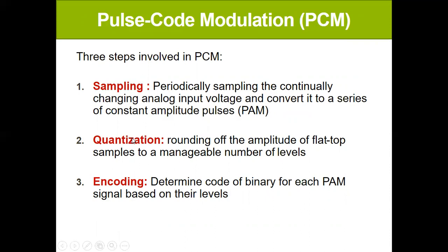Quantization is rounding off the amplitude of the PAM signal, in terms of flat top sampling, to a finite number of levels so that it is manageable.